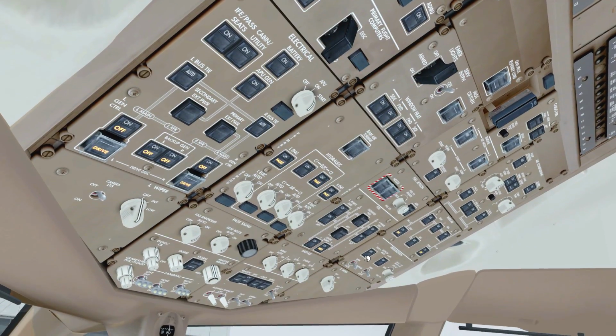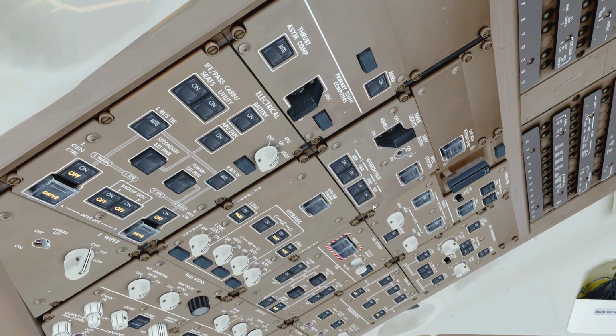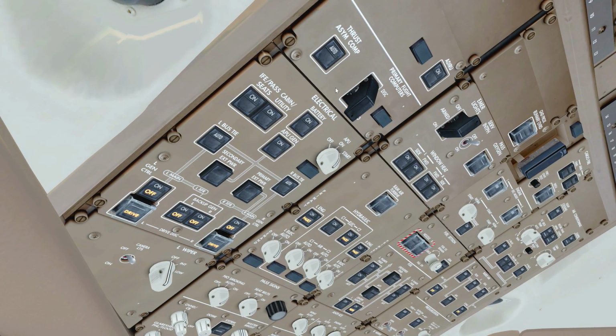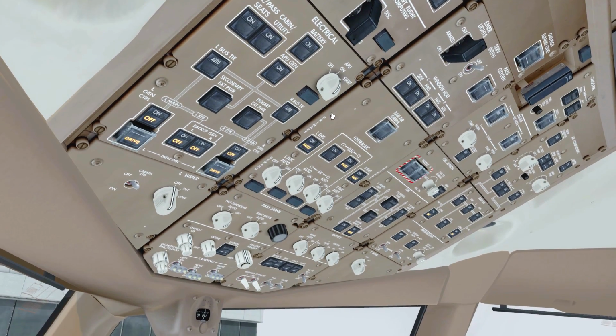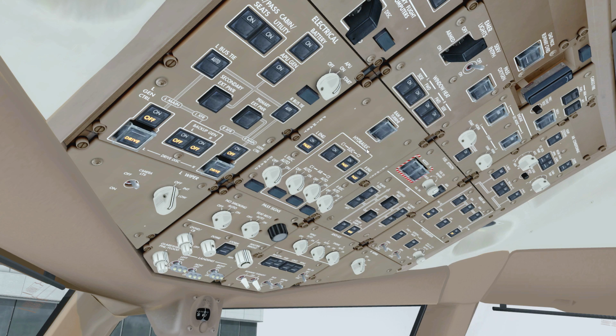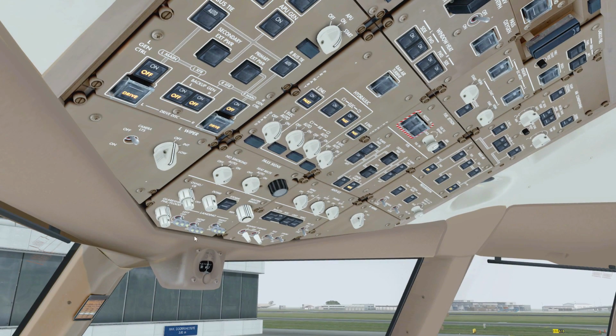So now that the hydraulics and the fuel pumps have been set, you can just do one more check of the overhead panel, again column by column. So all the electrical systems are set. Once the engines take over, the generators will run automatically, that's all fine. Window heat, emergency exit lights, that's all armed, that's good. Hydraulic panel is set, all the passenger signs are set. There we go. Our cargo fire has been tested. All the fuel pumps are on. We're going to turn on the beacon lights because we're going to be moving the aircraft shortly, and the packs will be taken over by the engines automatically in a minute as well.